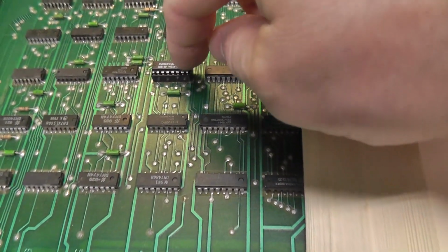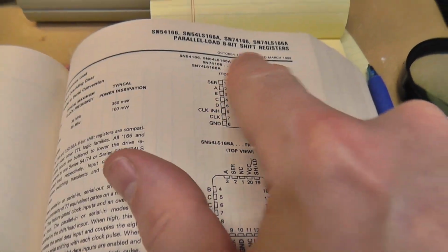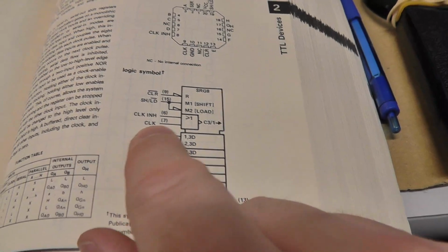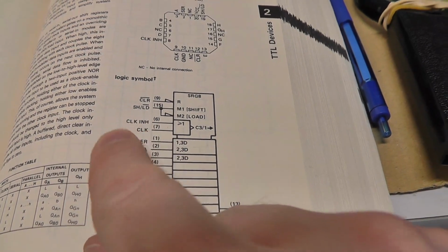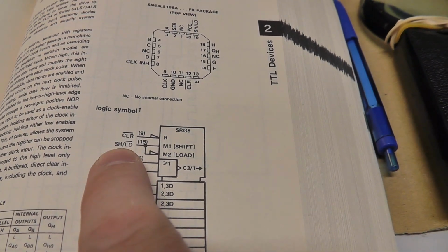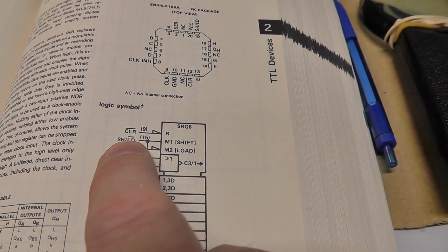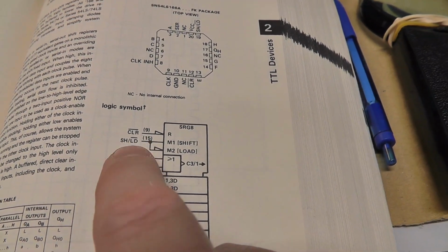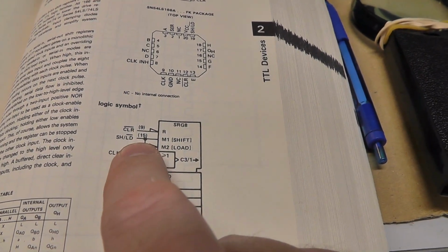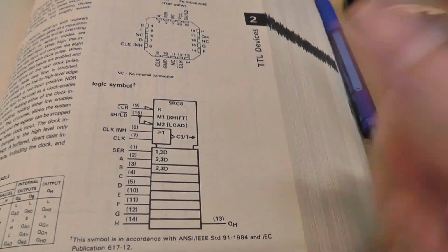All right, coming back to the 74166, which is an 8-bit shift register, parallel load, it says. I don't even know what that means, but 6 and 7 are basically clock inhibit and clock or something. I'd have to read exactly to figure out what this is. But regardless, that clock looks good. We got 5 megahertz there. But I was wrong about 6 and 7 being shift and load. It says S and L on the schematic diagram, but here that 15 is the shift and load. If 15 is not toggling, this chip isn't doing jack crap.